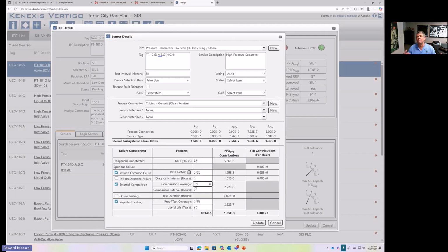at a frequency where we're going to use a little bit of judgment, a little bit of sanity and gut feel to say, okay, once an hour I'm going to want to see that kind of variation in the process signal. Once an hour is probably a good item to use. If you back off to once a day, it's a whole lot less effective, because the question you're going to ask yourself is, how long can a component have failed in place and the measured variable not moved enough for you to diagnose that you're stuck in place?